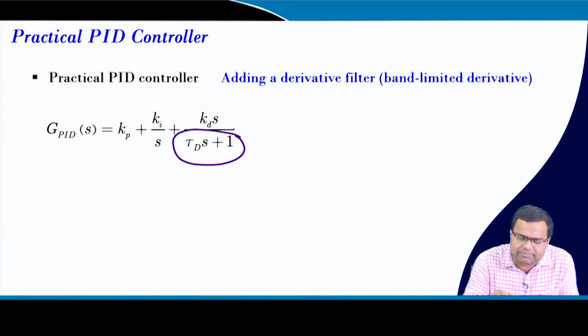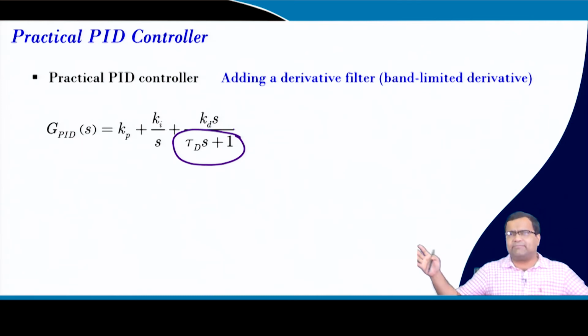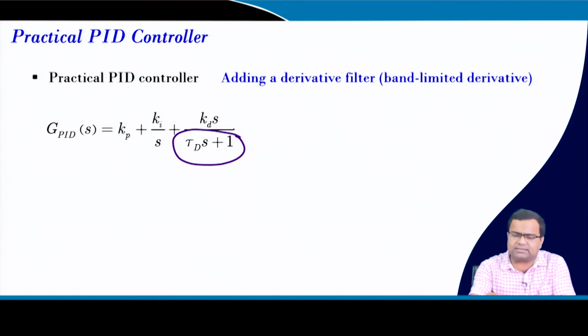But we generally take an op amp with a very high bandwidth, so we place this derivative pole as a filter pole as per our wish, because we need to choose this pole in order to meet certain requirements. So that is our design choice, where we are going to place this derivative filter pole.